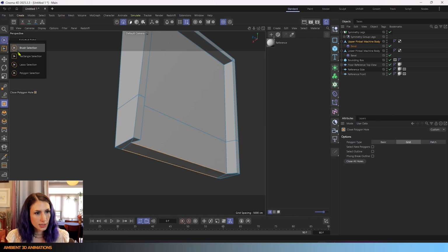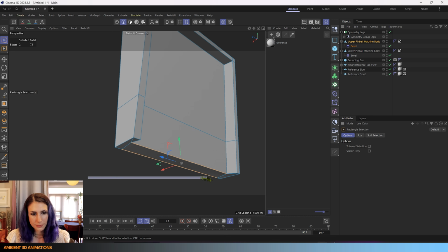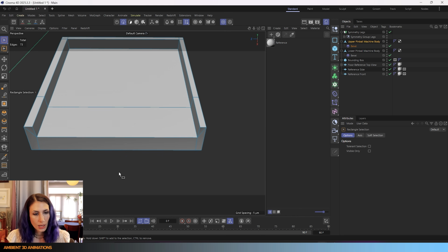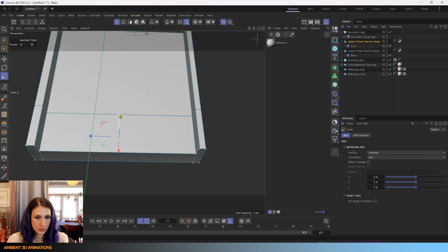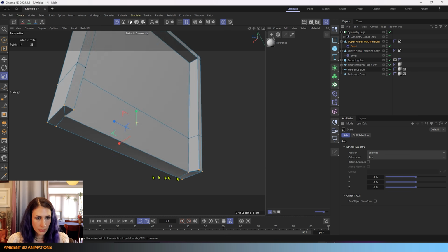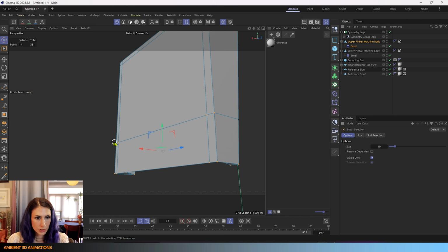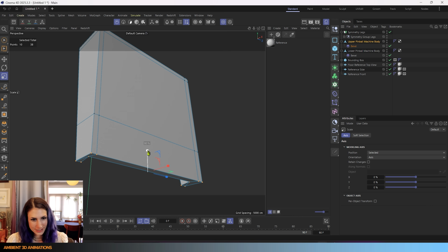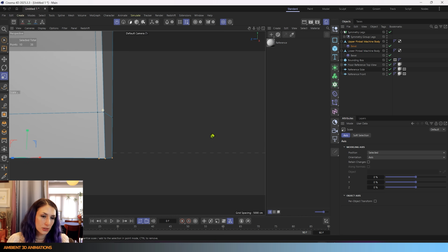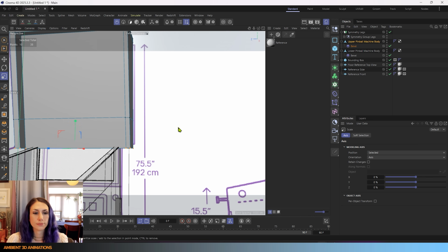So now we got that in there. And you'll notice that this doesn't look very flat, so if we're feeling fancy, we could use our flatten tool on these bottom polygons. Another option is we could just grab the points, use the T hotkey for scale or transform. I want to make sure that I'm not selecting more than what I meant to, which I did, so I'm going to deselect these guys in the back. Use T, and then these should scale down to be 0%, which is also completely flat. Sometimes I'll do that instead of grabbing the flatten tool.